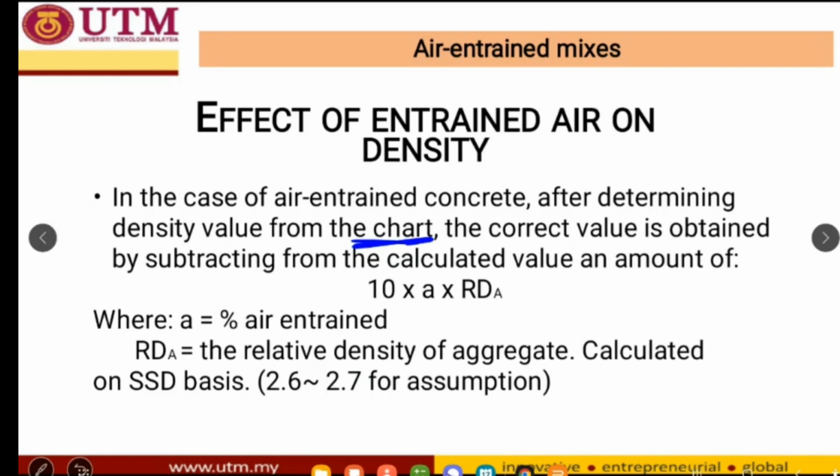A, like what we have already discussed earlier, is the percentage of air entrained, whilst RDA is the relative density of aggregates, which is calculated on an SSD basis.